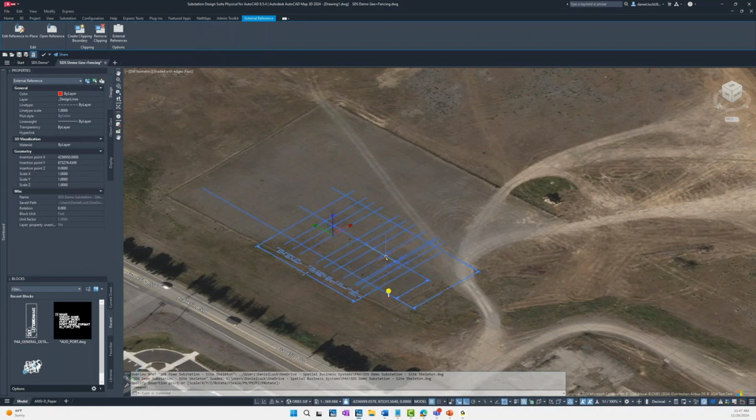instantaneously. And another big part about the XREF command is these XREF drawings are not actually part of this drawing, of this model space that we're working in now. They're just attached to the drawing, externally referenced. So the big advantage is it doesn't increase the file size of the base design.